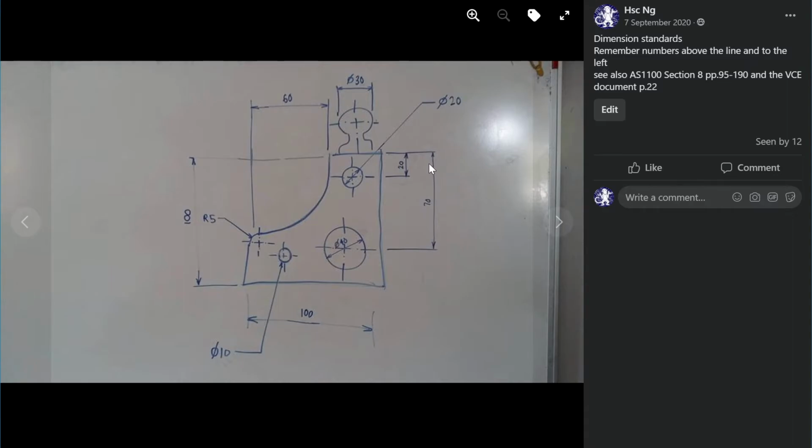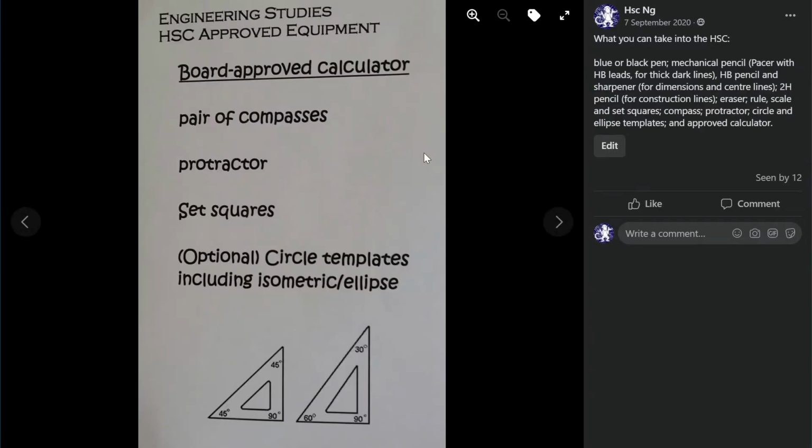When we draw an arrow, the arrow should be 3 millimeters long and 1 millimeter wide. The dimension line should never touch the object. There should be a little line that sticks out past the arrow called an extender. I like to have a 1 millimeter gap and a 2 millimeter extender. I think that's pretty much everything with dimensions. I have the page numbers that you can look for here. Hopefully that should already be on your page.